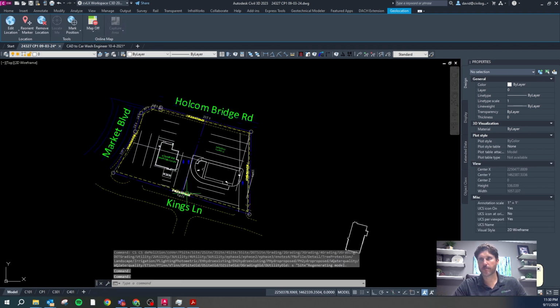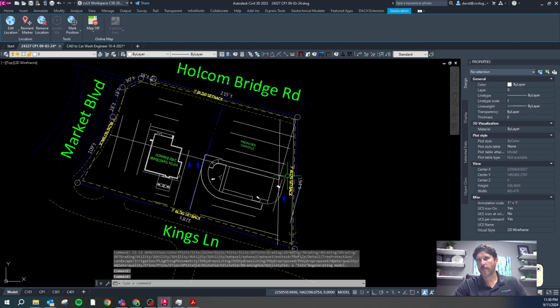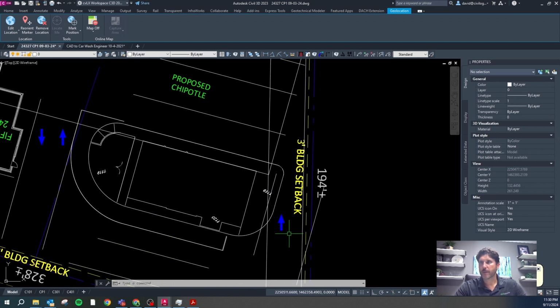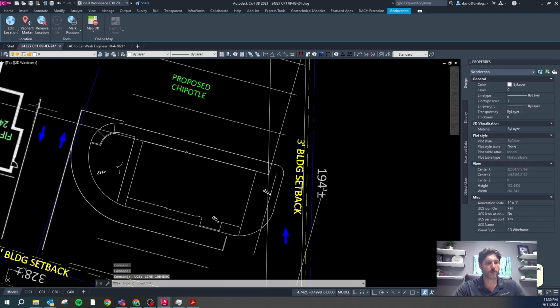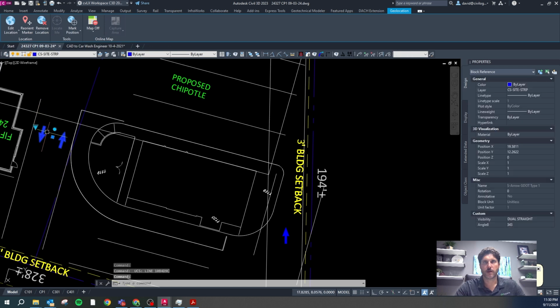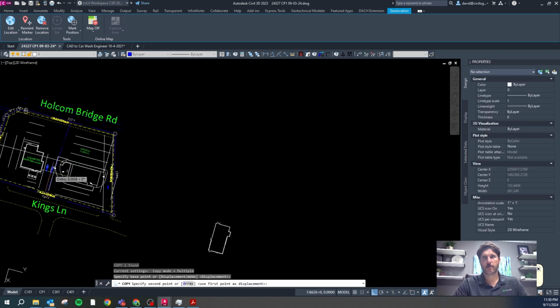Okay, going back to the site plan. All right, so we have almost a wireframe. We need a little bit more for it to be a wireframe. This is going to be a one-way here. These guys are going to be, one trick, you can set your UCS with Control-Shift middle button to this, and then you can just grab this thing, and when you have your UCS on, or your ortho on, it'll just snap and be perfectly aligned. So that one's going to be like that.